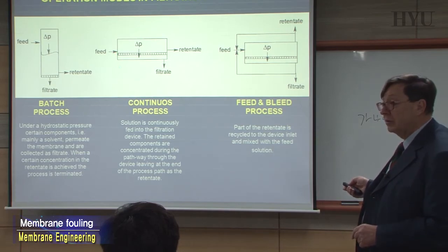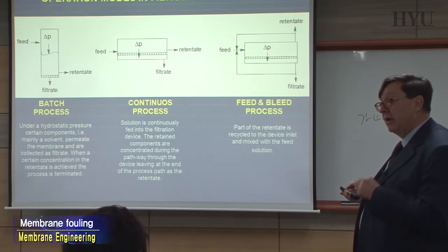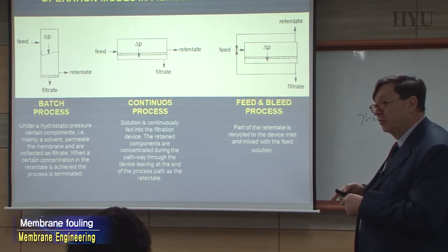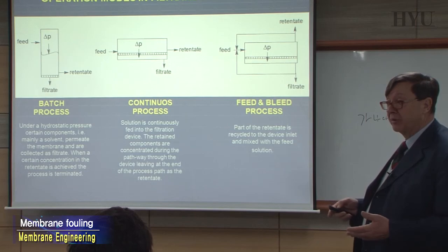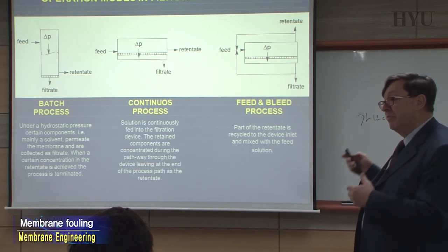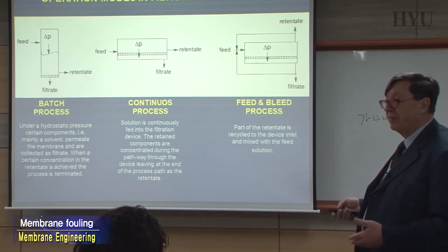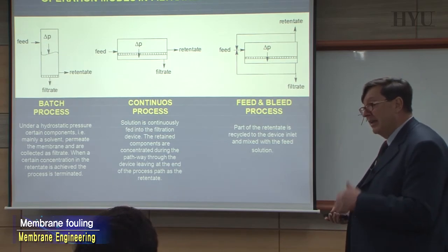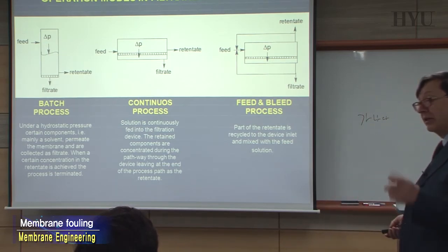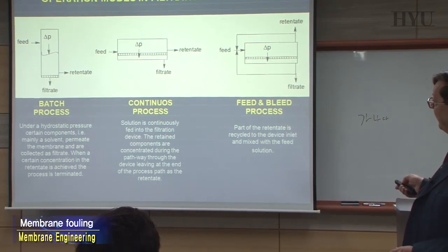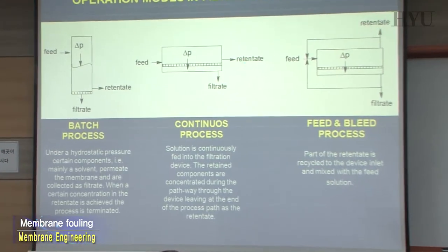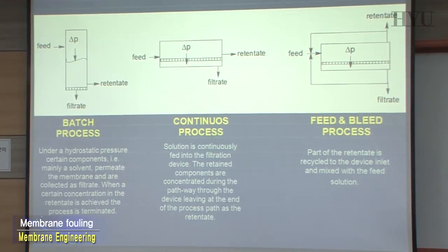Membranes are always in cross flow, and membranes are quite interesting because you can move from a batch system to a continuous system, and that's very important. Fermentation, some big plants, or production of emulsion, etc., can be redesigned as a continuous system, no more as a batch system. And this is the traditional way of doing it, in which you just have your feed, and as you know, we apply a driving force, we have something going through and something that is the concentrate, which we can eventually recycle.